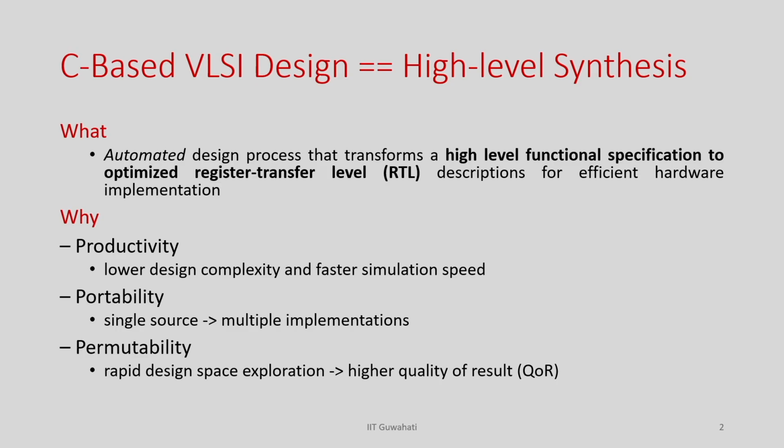Just to start with, we have already discussed that C based VLSI design means the VLSI design flow starts from C code and then we convert it into RTL, and from RTL we do the gate level transformation by a logic synthesis tool, and from gate level to transistor level by a physical synthesis tool and so on, and then finally we get the chip IC after fabrication.